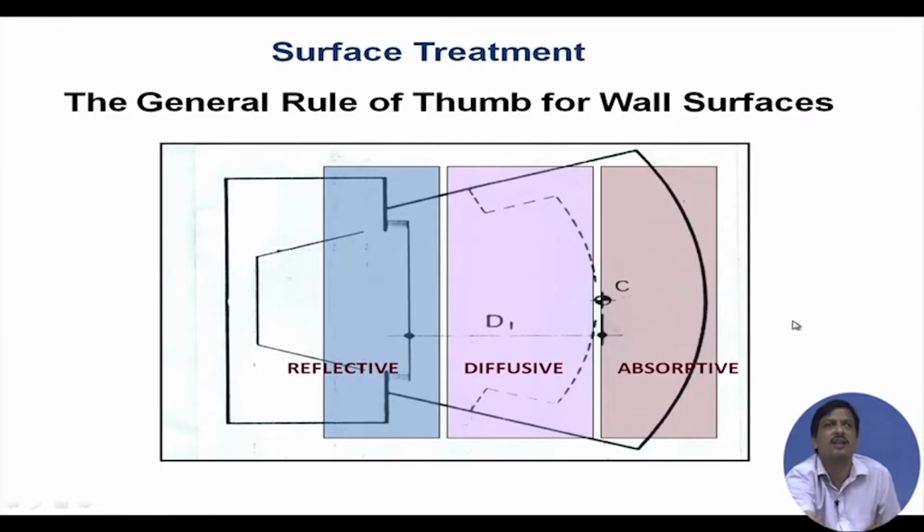Okay. So, that is the thumb rule for acoustic treatment in any auditorium. If you have visited any good auditorium, you will have found that the front part of the stage is made of polished wood with some channels. The channels create a diffusive reflection, and the polished wood is reflective, glazy.